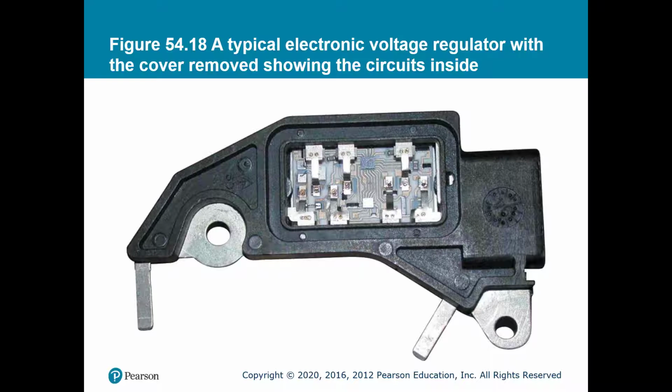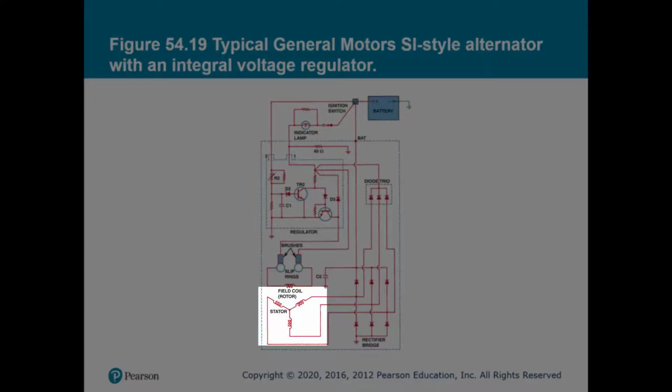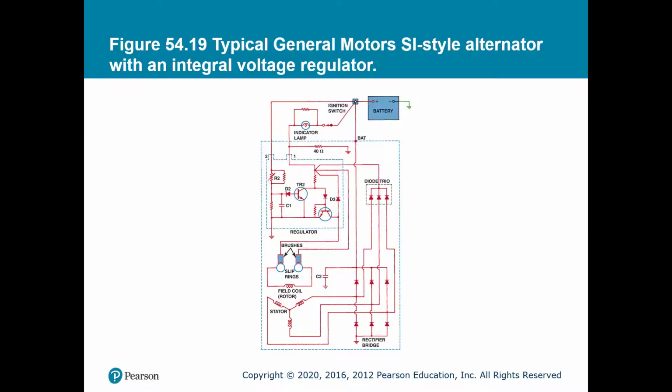But these are pretty reliable. This is a diagram of the circuitry that's in the voltage regulator. And you'll notice the way that the stator is wound, it is a Y winding. So there's your stator in the lower left-hand corner. And this is basically the circuit that controls the regulation of voltage.